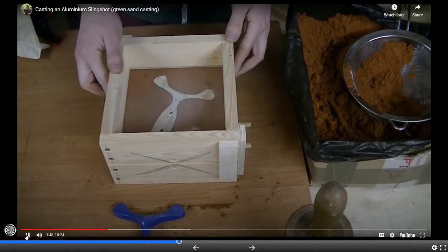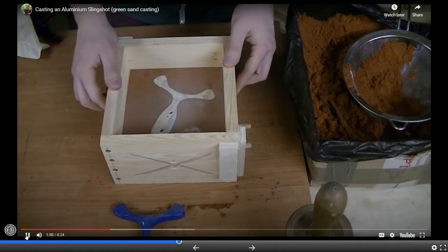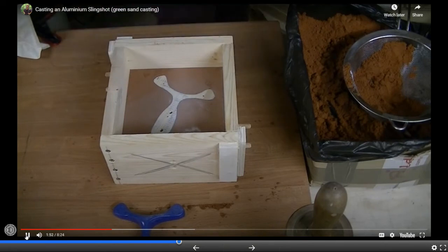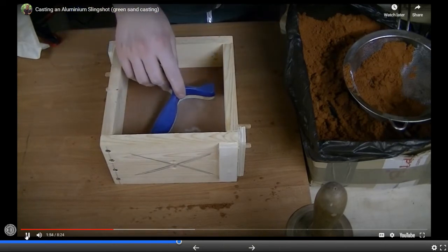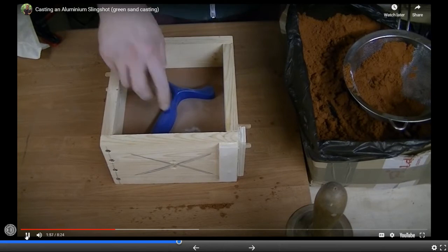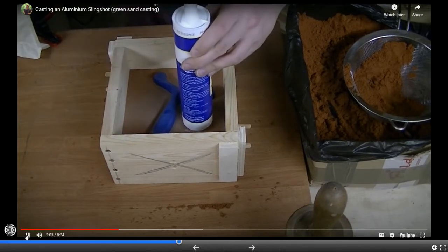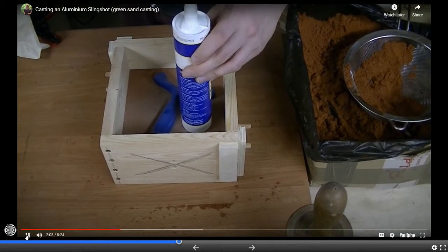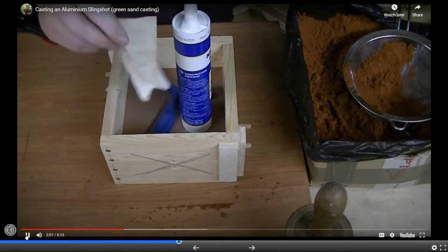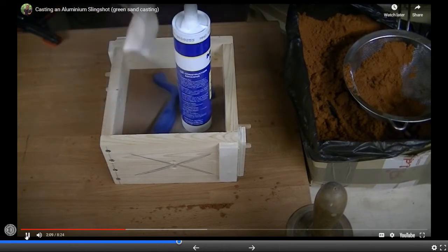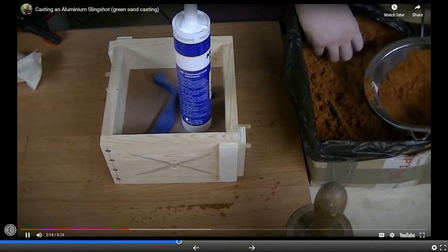There's a top half of the mold, which is called the cope. Now the second half of the mold can be made in similar fashion, only that I added a silicone cartridge to form the sprue for pouring in the molten metal. Here he's just using something, anything, to hold the space to form the sprue, which is a column that leads down to the gating system that goes to your main mold cavity. So he's using this to hold the space for the sprue.